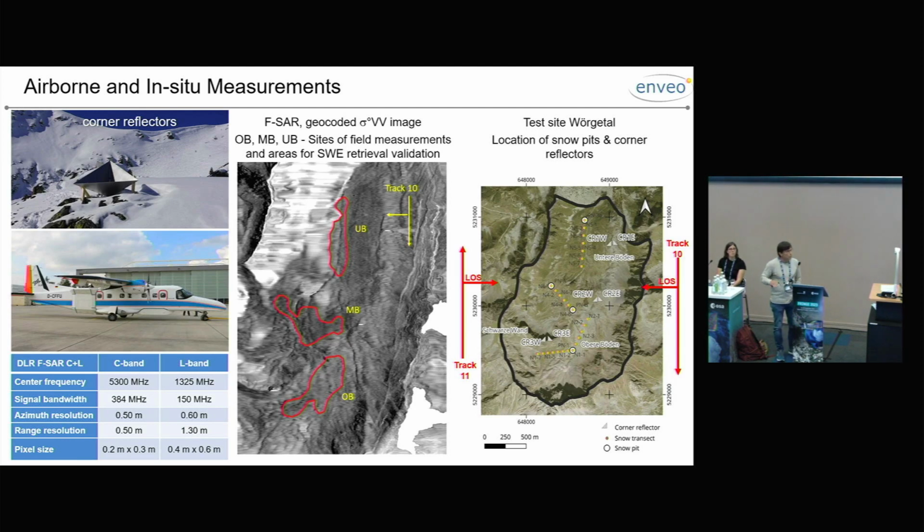They are homogeneous regions and flat terrain, selected based on the digital elevation model and also the surface vegetation. We set up a couple of corner reflectors in the test area. They look towards the ascending and descending tracks, so always one pair on each side, oriented towards both sides, and we need this as a reference for the phase. At every overflight, these corner reflectors were cleaned of snow and remeasured in order to guarantee their elevation angle and orientation.